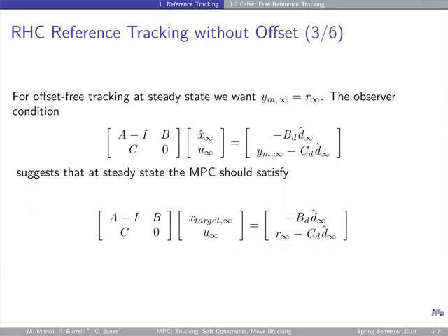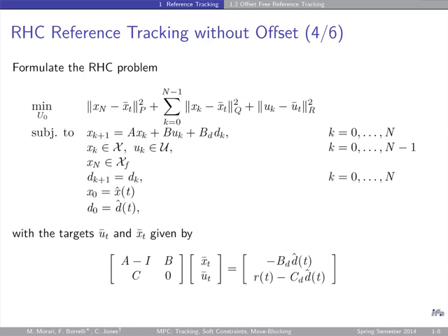So, as it says here, the output constraints are really hard. Furthermore, the output constraints lead to a lot of complications in the controller design. They lead to all those sets that Professor Borelli introduced. They are essential to understand the range within which the controller can operate, which obviously depends on model knowledge. So output constraints make your job very hard in terms of the theory. And then you say, okay, why make my life so hard if the output constraints aren't hard in reality anyway? Therefore, in industry, most applications don't put in hard output constraints. They put in soft output constraints.